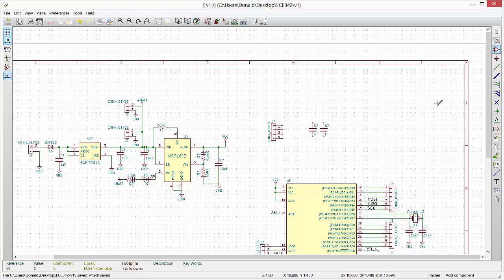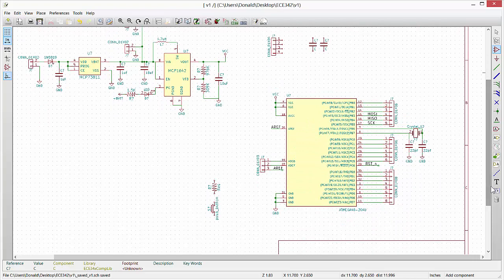So one of the things that's important when you're laying out a digital circuit is to make sure that your various digital ICs have local capacitors very close to their power and ground pins. And these capacitors act as a little bit of local energy, so that if there's noise in the power supply line, or if the chip itself needs a little bit of extra energy right then, there's a reservoir waiting near those. Sometimes these are called crap caps because they remove the crappy voltage levels from the voltage line itself. They don't remove it, they supply energy to counteract it, would be a more accurate term.